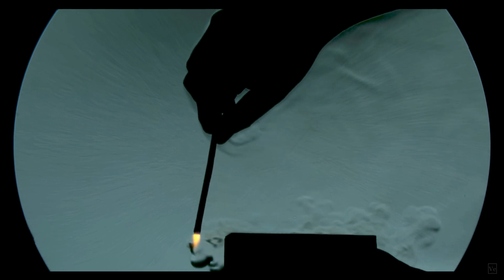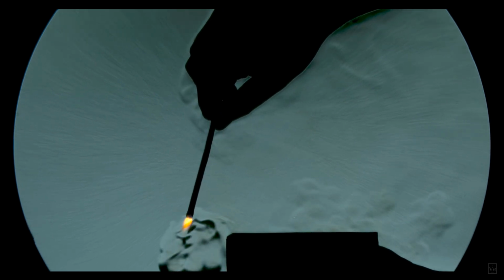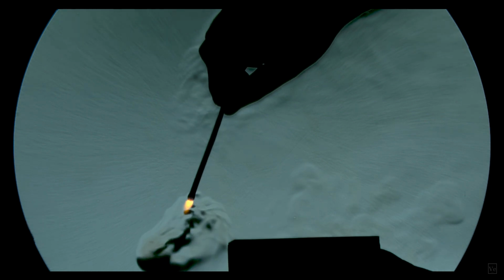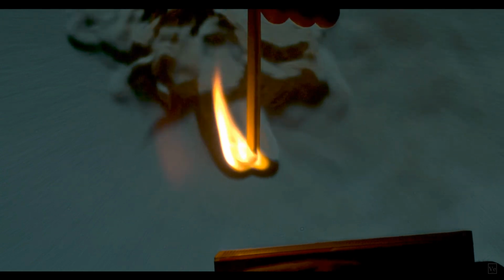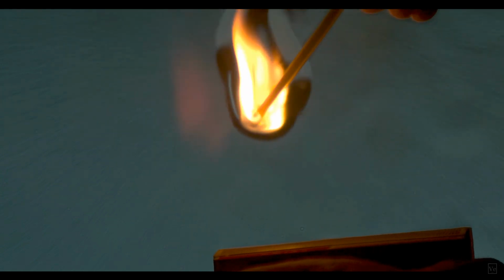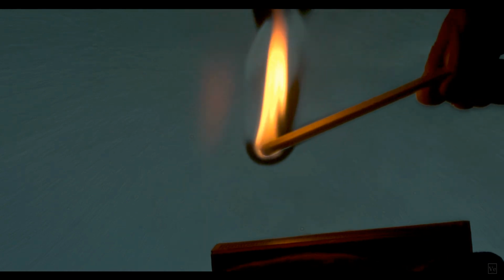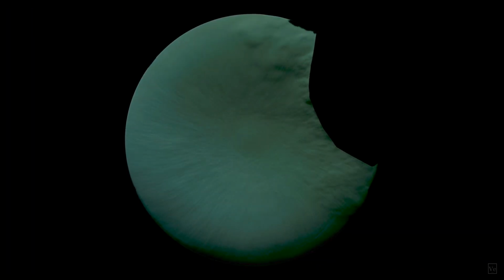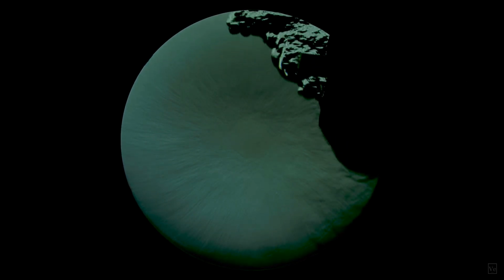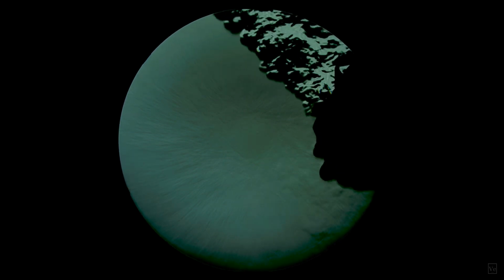And so one of the things you'll see in this is that phenomena that generate heat, like the striking of this match, or even the hand that's holding this match, those regions of higher thermal energy are going to tend to boil upward. Okay, this thermally induced buoyancy, which is very apparent right here. And what's less obvious, because it's not a strong temperature gradient, is that cooler fluid is rushing in to fill those voids left behind by the motion of the hotter fluid. So these are classic cases of buoyancy-driven flows. I'm not actually sure what we're looking at there.